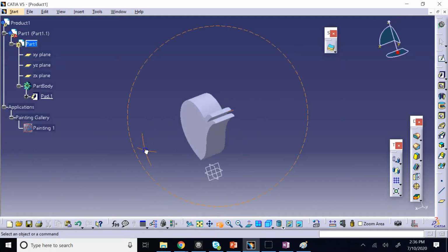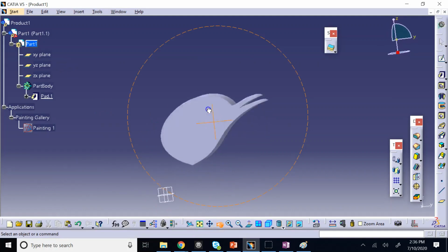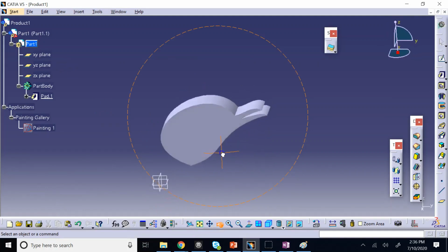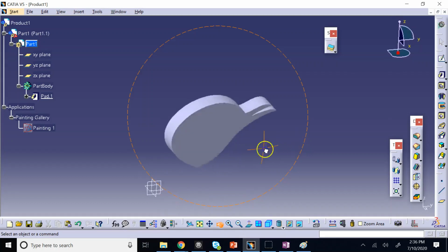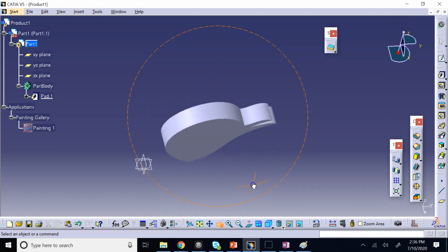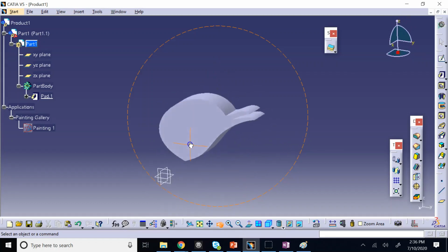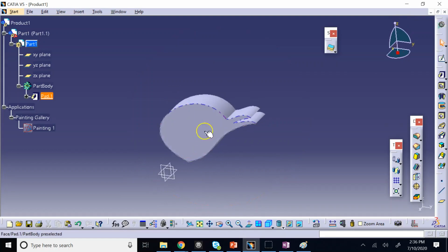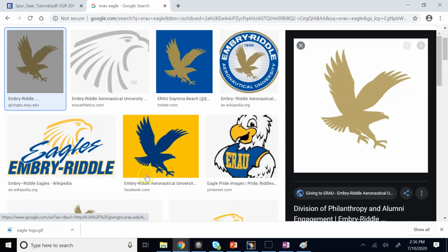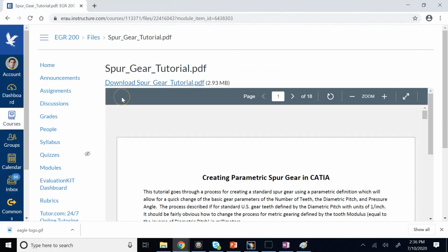So this is the method that you use for tracing sketches and creating a replica of a part, which is just a simple extrude where the cross section does not change. Not all parts are like that, so not always can you use this method, but if the parts are simple extrudes with complicated profiles, this is an extremely useful tool.